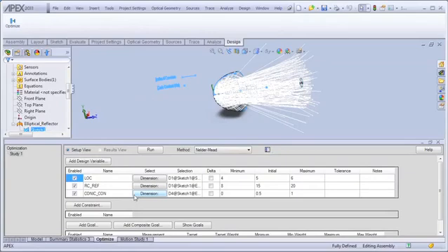Setting up an optimization study in Apex involves these essential activities: defining variables that can modify the specified geometry, setting any desired constraints, which create direct or indirect relationships among the design variables, and possibly the merit function used to limit or restrict the variable range, defining goals, which are some type of performance target you wish to achieve, and then selecting the surface measurement to which a goal is applied, running the automated optimization process, and then viewing the results on the Active Study tab.